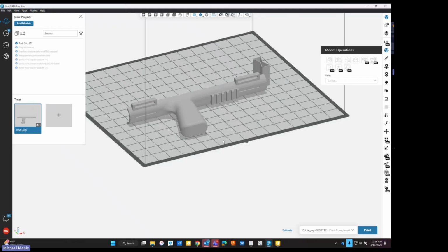One thing to go along with that, as far as the 3 inches or less, the reason that they build with model material is because of the different shrink rates between the model and the support material itself. And if you build, say, an 8-inch tower out of model and support, by the time you get to that 8 inches, the support's actually going to be a little bit low because it shrinks more than the carbon-filled material. Because of the carbon, it doesn't shrink as much. But if you break it up into 3-inch chunks, then you're going to be okay.